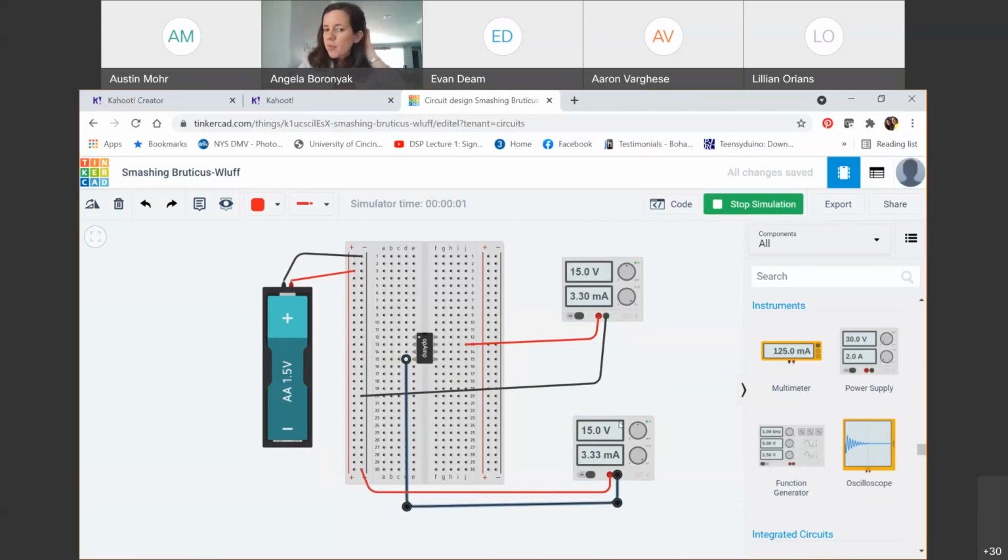Now if I compare them, both of them can do that. Okay. That's powering my op amp. Questions or concerns on that? Because again, it's a little tricky when you can't make an actual negative voltage. You have to flip the terminals of your voltage to make it negative.